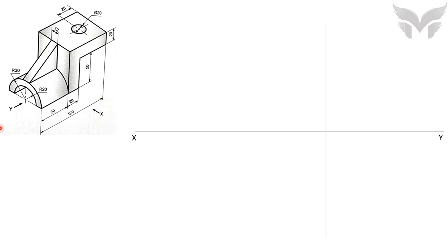Alright. Before we actually start drawing the front view, you need to make sure that you will have enough space on all sides of the front view to give dimensions. And to do so, you need to draw a faint parallel line just above XY at a minimum distance of 20 to 25 mm. Remember, it's a minimum distance. Similarly, draw a vertical line with the same spacing to the left of the previously drawn vertical line. Perfect. Now we are ready to draw the front view.